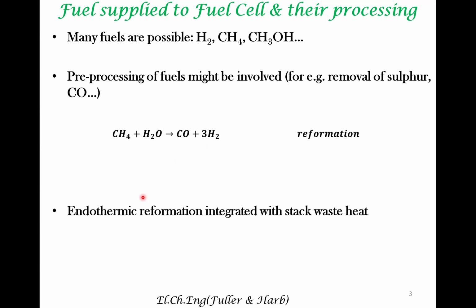Reformation reactions are endothermic in nature. You need heat to run a reformation reaction. So the waste heat from a fuel cell can be integrated with the reformer so that the waste heat is utilized for running this endothermic reaction. This heat integration improves the energy efficiency of a fuel cell.